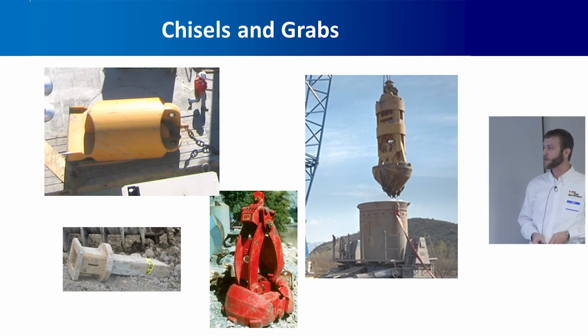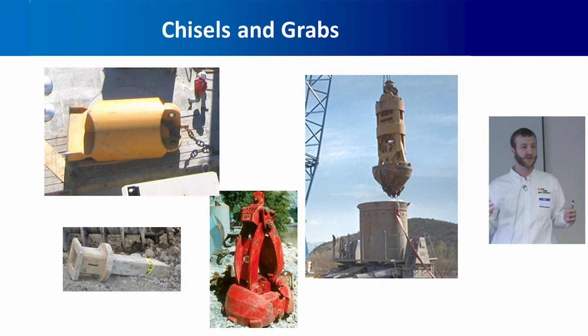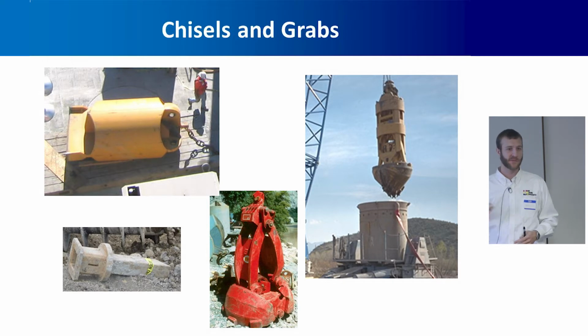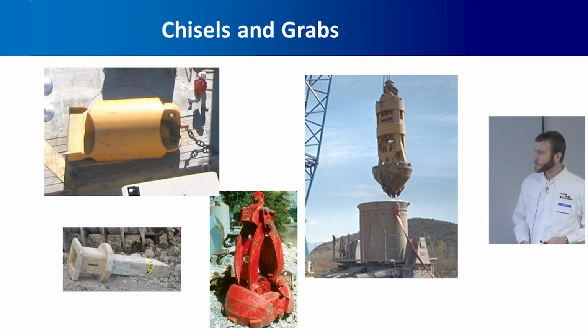So, some of the non-rotary tools: chisels. Maybe you've cored some rock, but the rock cores aren't coming up in big solid chunks, so we need to bust them up to be able to get them up on an auger. So you just pick up a chisel and bust up the rock. This is a chisel that you would pick up just on a crane. This is a type of chisel that you can attach to the Kelly bar.